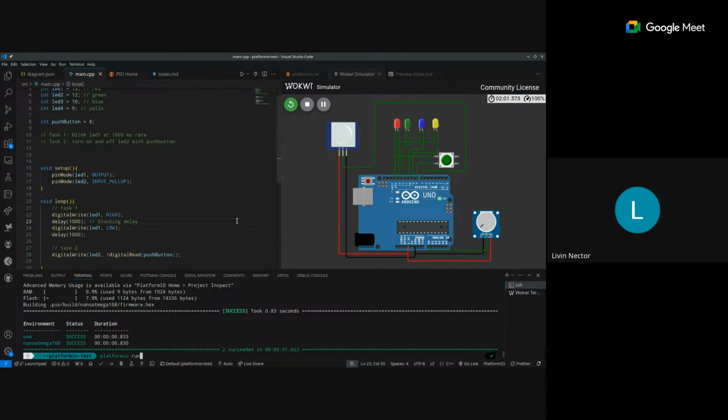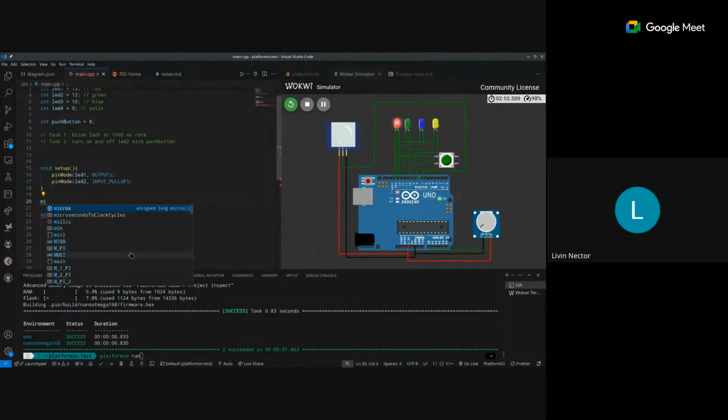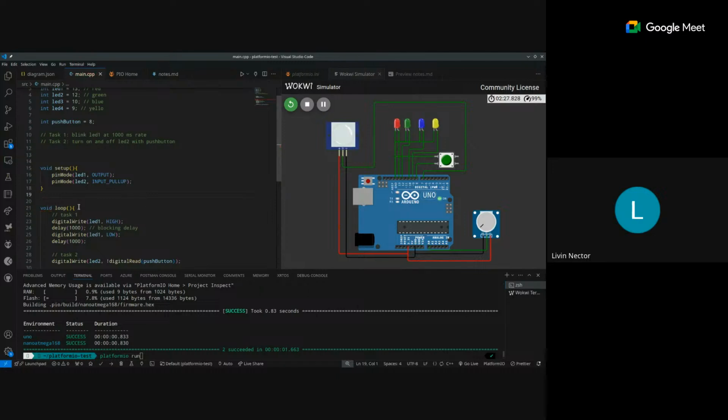Okay, now how do we do that? So here in the Arduino API, they provide another function called millis, and there is also micros, if you see, which is microseconds. This millis function returns the number of milliseconds that have elapsed since startup. So that's what millis provides. What we usually do in case of this blocking delay is we store the last time the state changed, and when it is actually time for the LED to blink, then only we change the state.